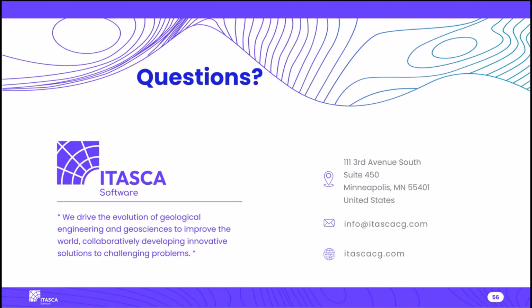Next question. Thank you for the presentation. For the conical embankment example, what is the main advantage of using Maxwell damping? Was it to reduce the runtime, larger time step? If so, how much larger time step were you able to use Maxwell damping for the conical embankments?